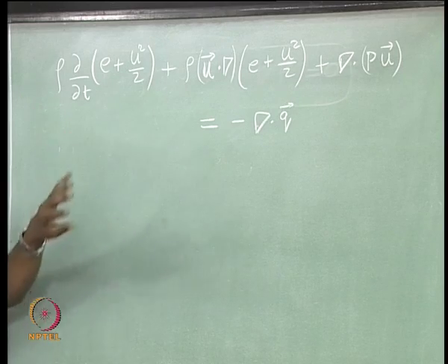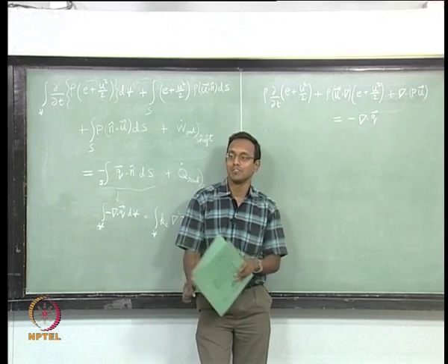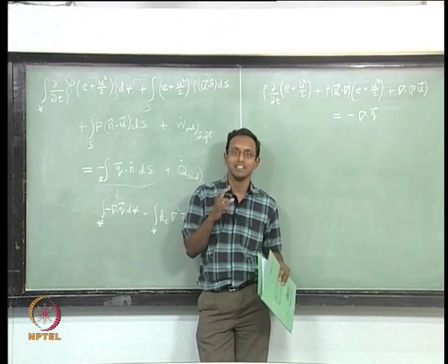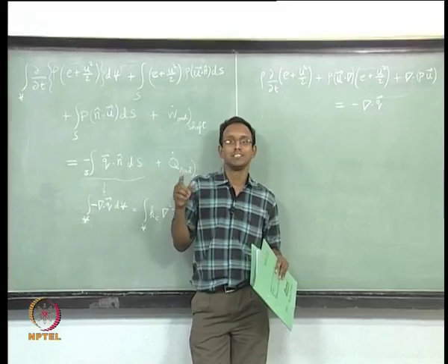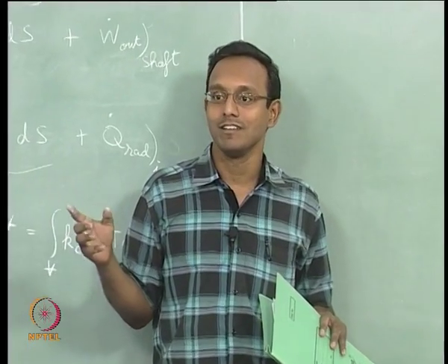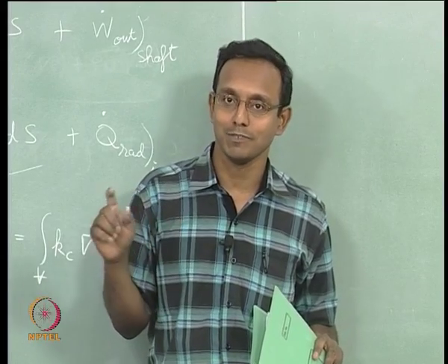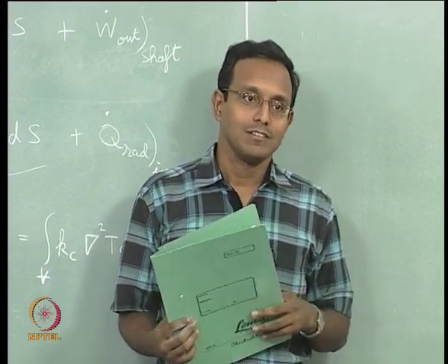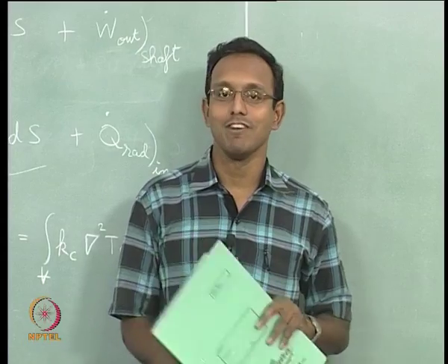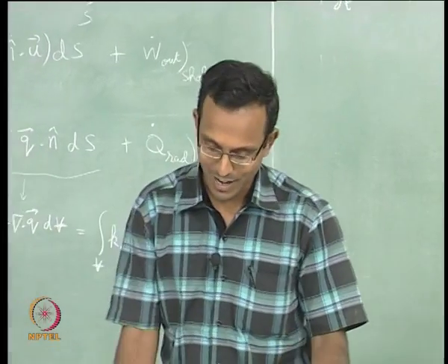We will keep all these forms. Now we are at a point where we have all the governing equations for the flow. Along with this, we should keep the equation for entropy, that is T ds equals dH minus V dP. We have to keep that form, or du plus P dV, not du, for you it will be dE, the change in internal energy, plus P dV. And P equals rho RT, the gaseous equation of state. So ideally we have 5 equations. We will look at what happens when there are 5 equations.